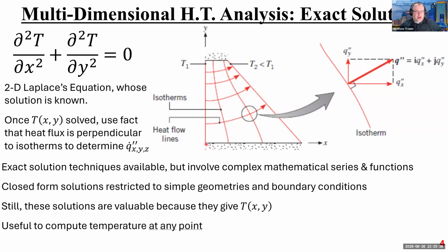In this particular setup, we have an adiabatic surface here on the bottom. We have another adiabatic surface here on the top. We have a line of constant temperature fixed at T1, an isotherm at T1, which is basically this vertical line here. And then we have this other line, which is also an isotherm, constant temperature at T2. And notice we have this two-dimensionality, right?